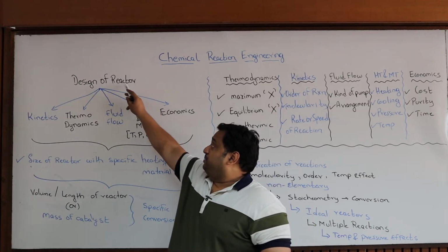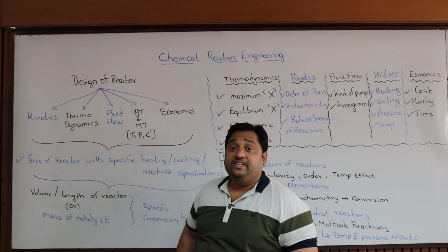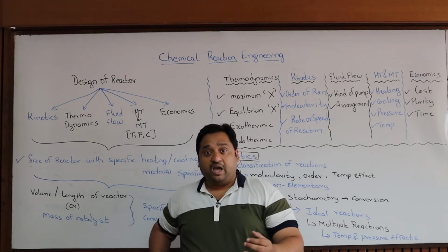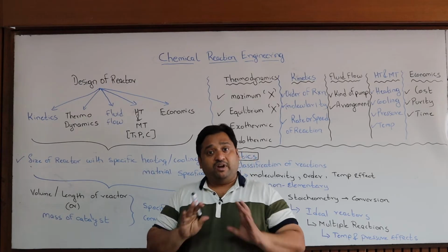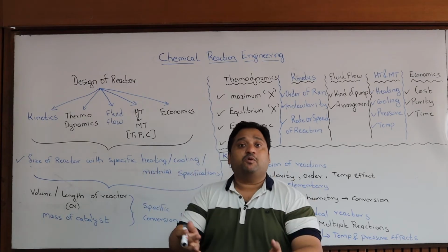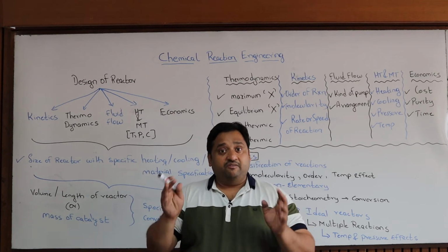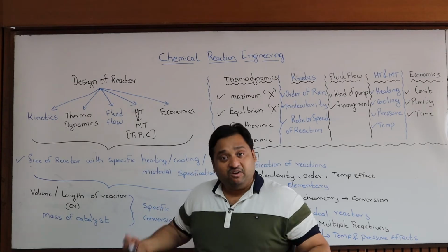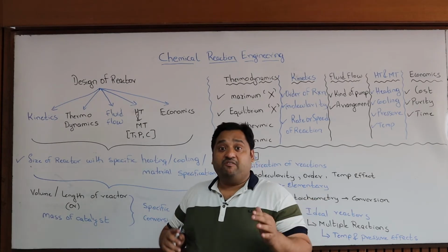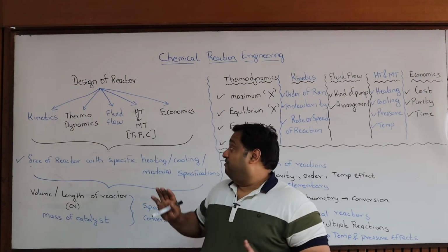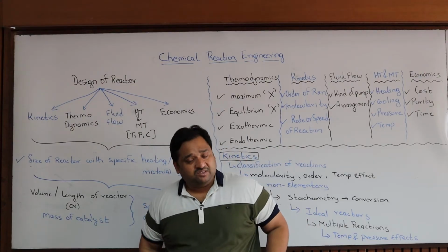And what is the other aspect of designing a reactor? Is it an exothermic reaction, where heat is getting produced, or an endothermic reaction, where we are going to supply the heat? What kind of requirements we have to provide, a jacket for heating or a jacket for cooling, depends upon the kind of reaction and what temperature we have to maintain inside the reactor. Depending upon all the requirements, we have to go for heat transfer and mass transfer processes.